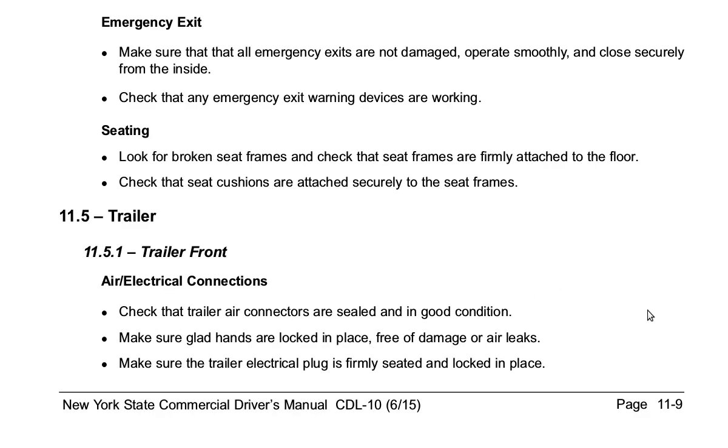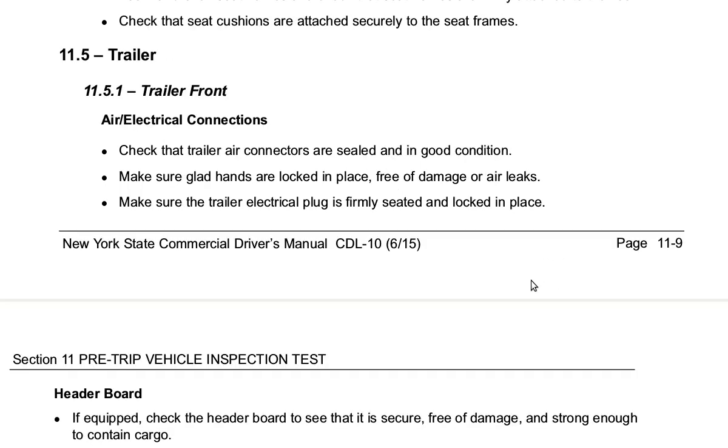Trailer front. Air electrical connections. Check that trailer air connectors are sealed and in good condition. Make sure glad hands are locked in place, free of damage or air leaks. Make sure the trailer electrical plug is firmly seated and locked in place.